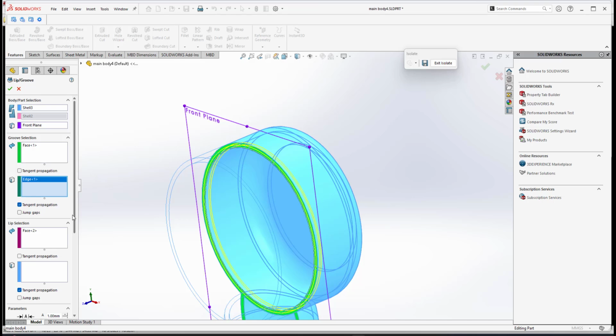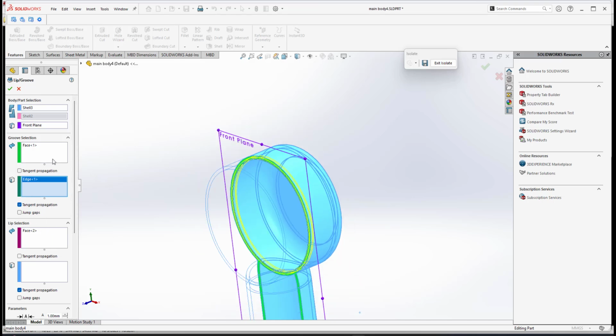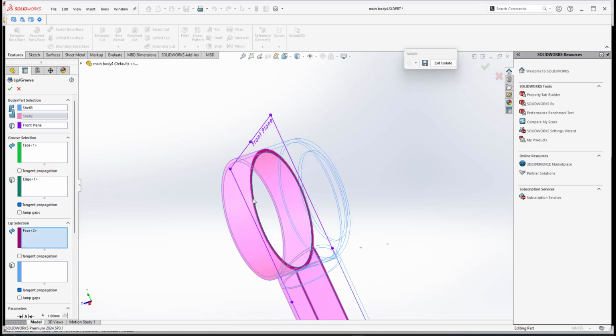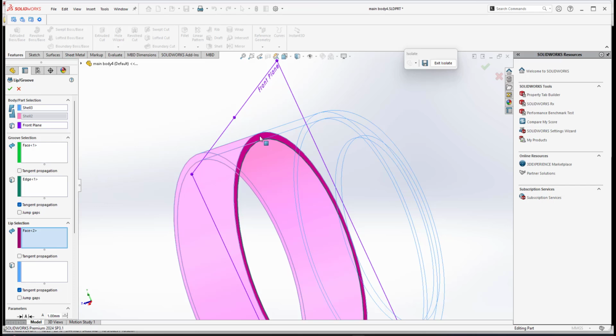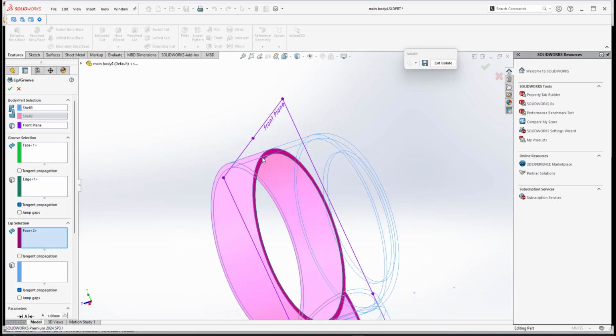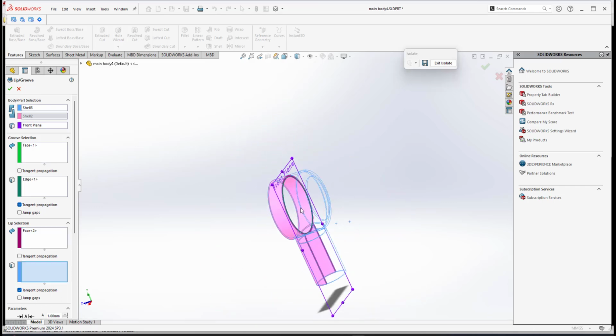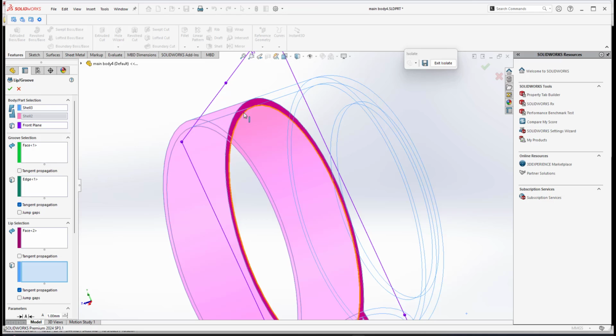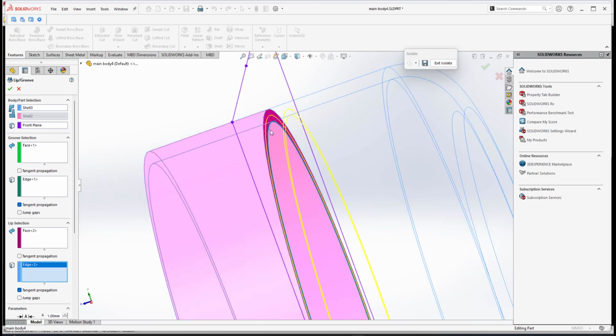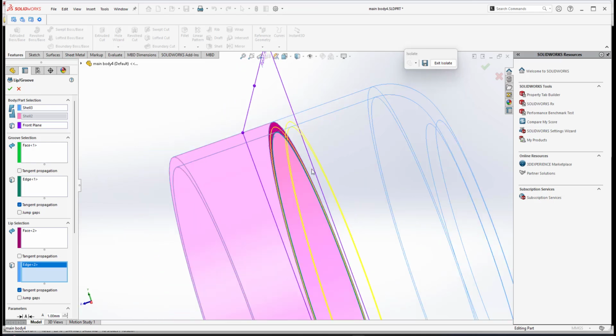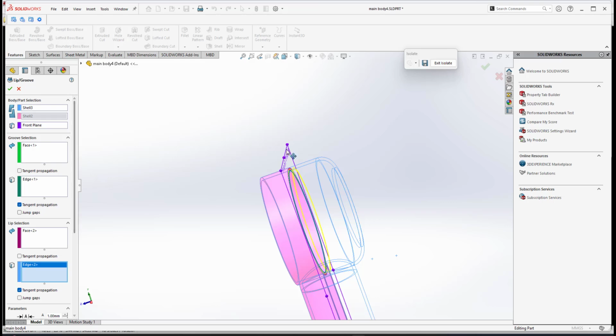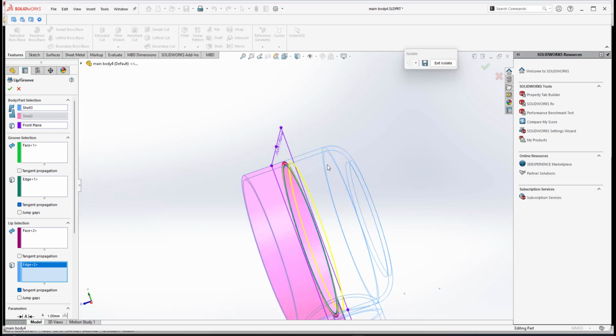That was under the groove section. If I click the lip section now, I select the face of the front part where I want to create the lip. It is already highlighted here as face 2. Then I select the edges of this front part that I want to create as the lip, so I select the inner edges. As you can see, it already creates a preview, with a protruding piece. This will be the lip. Previously, at the rear part, we created the inverse cutout, the groove.